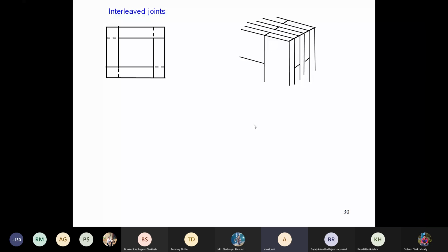But sir, only at the corner they will be in contact; in the middle, I think there should be a gap of air. In the middle, there will be insulation. Between the two sheet steels, there will be insulation, because we don't want to make it a single piece of iron. Otherwise it will result in eddy current loss. Otherwise we could have made it a single solid piece of iron.